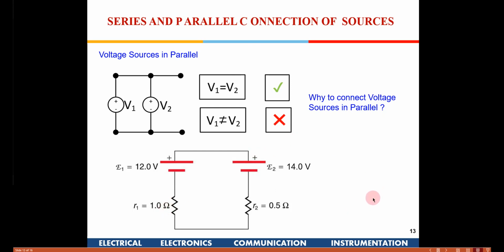And then you have a load also connected, so the majority of the current goes into the load from the source. Whereas for the battery, because this is at a higher voltage, most of the current will be given from the source and not from the battery. The charge in the battery will be preserved.